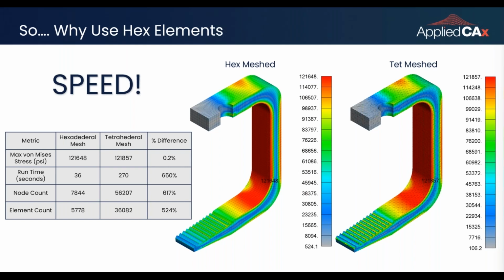The major advantage of hex is reducing our node count, so you really want to work with the linear version. So then you have a mismatch of some elements with mid-side nodes, some without, some tet, some pyramid, some hex. And you want to look and see each of those in the structure where they lie. You don't want those odd elements in your high stress region or a region with a high stress gradient.